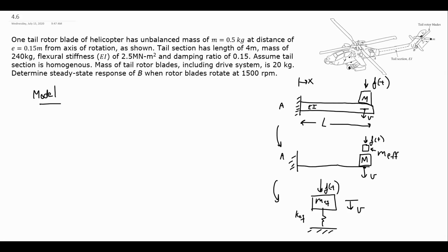So to get down to that bottom layer where we just have our equivalent mass or equivalent spring and we put the forcing on it, we're going to need to go through a couple of steps first. So let's first find, how do we find our K equivalent? Really we're using the idea of Lagrange here. We're still trying to find total potential energies and total kinetic energies when we do this. But the only thing in this system that is going to have stiffness is the deformable beam itself. So we can go and find its equivalent stiffness using the beam table.